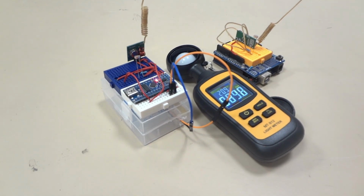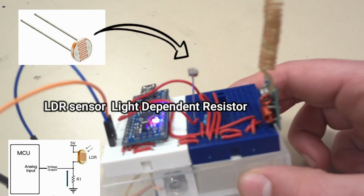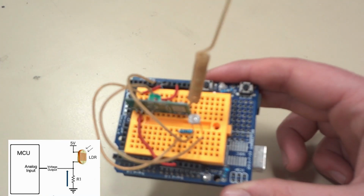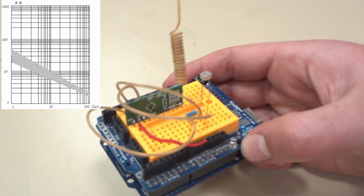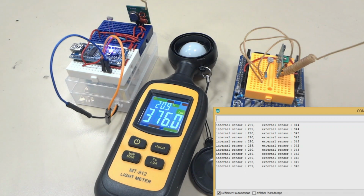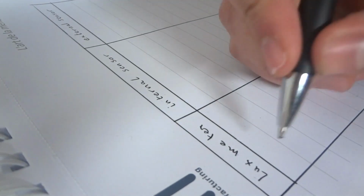The photosensor I used is the so-called LDR sensor, which stands for Light Dependent Resistor. With the Arduino's ADC, I read the output voltage of a simple voltage divider. The datasheet of the sensor tells that there is a linear correlation between the logarithmic function of the illuminance and the logarithmic function of the resistance, and that will be our reference for calibration.